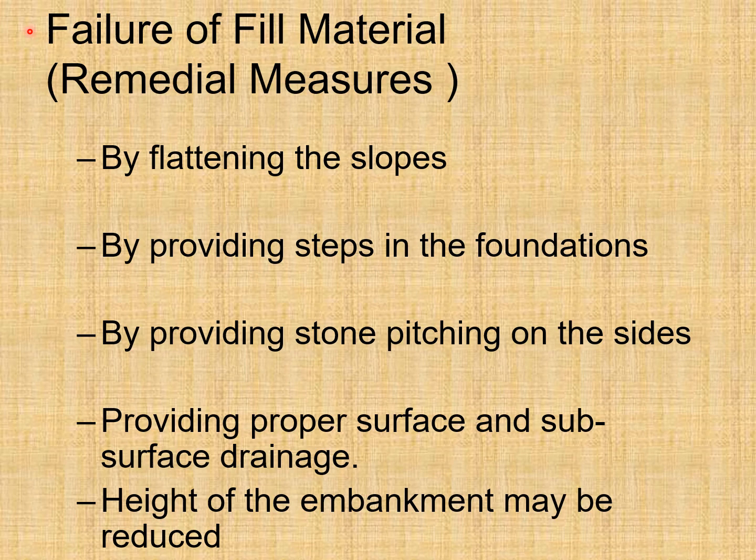Failure of the fill material, remedial measures: by flattening the slopes, by providing steps in the foundations, by providing stone pitching on the sides, providing proper surface and subsurface drainage. The height of the embankment may be reduced.